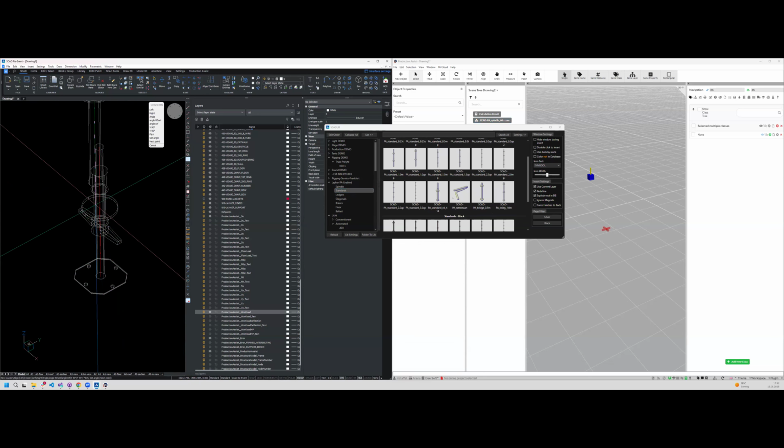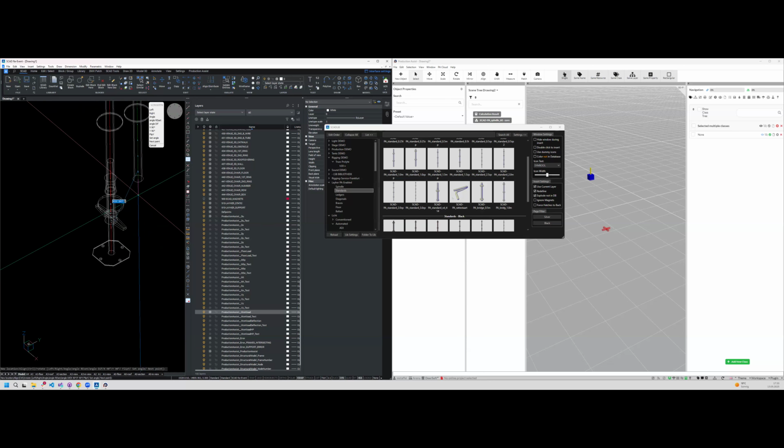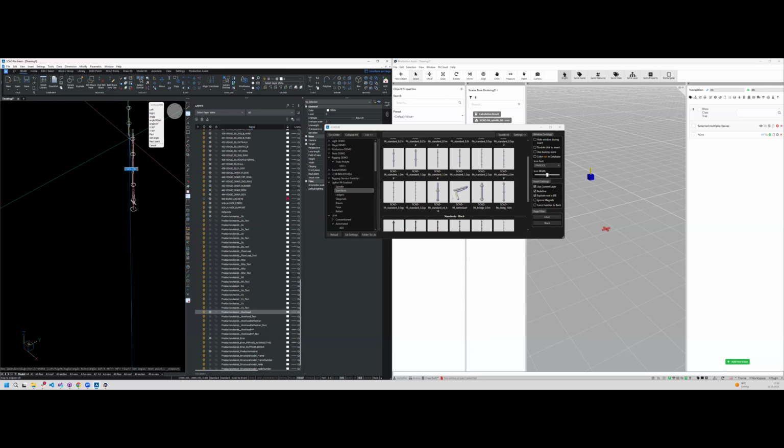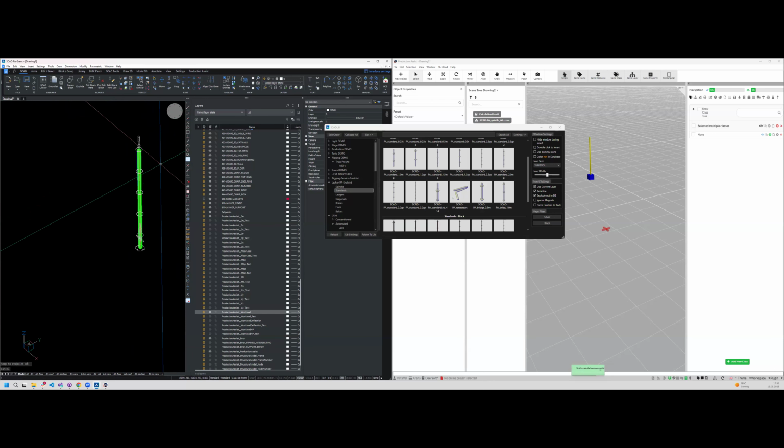The important thing that you use for the insertion of the layer is the object snaps in here, so the snap to point button. When you activate this, it will only snap in here. An important thing also is that if you change it during the command, it will also select the other pieces in here. But when you're snapping the layer, this is not something that you want. If I activate the command, you will see it automatically resets. So if you want to change it permanently, you need to do it without a command.